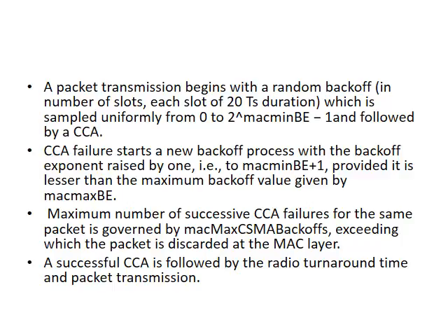So basically all we're trying to do over here is sense the channel, and only when the channel is free do we send the packet. Otherwise we wait for the channel to be free and then send the packet. So a successful CCA is followed by the radio turnaround time and packet transmission.